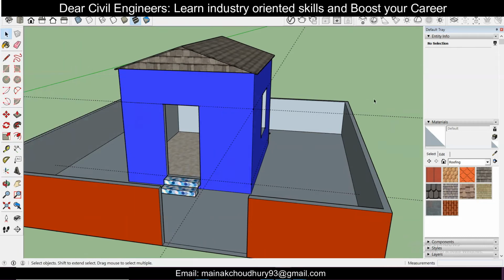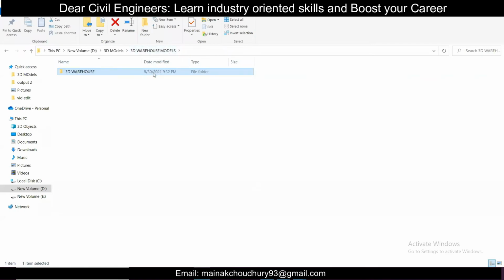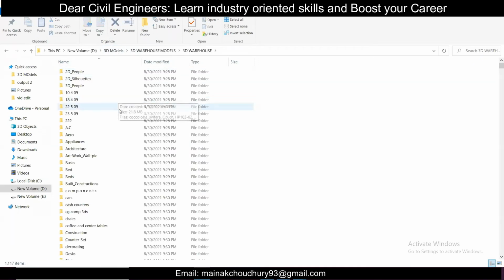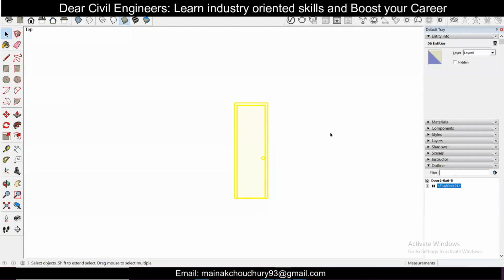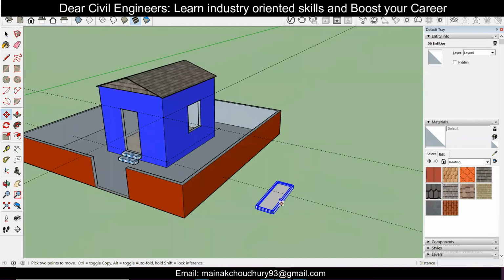And if your warehouse is not working for some reason, I have given a link where you can find all these models. In these 3D models, you can just download it and then select whatever you want. Suppose I'm going with doors, and I'm going with door 2, and just double click on it. It will open here like this. This is the door 2. Then press Ctrl plus A to select this entire thing, and then Ctrl plus C, that is copy, and then come back to your model and press Ctrl plus V. So it will paste the door here.